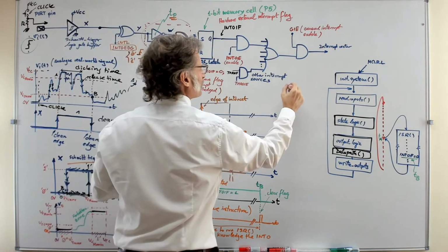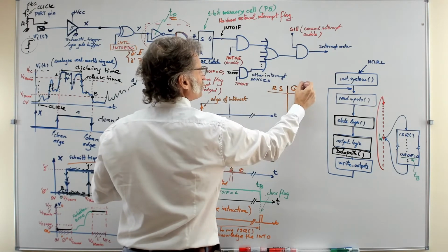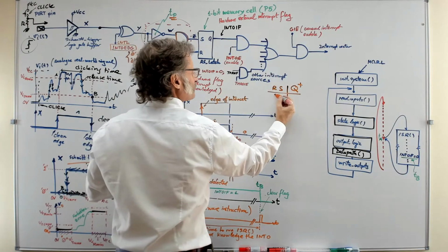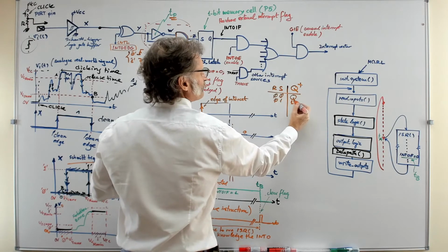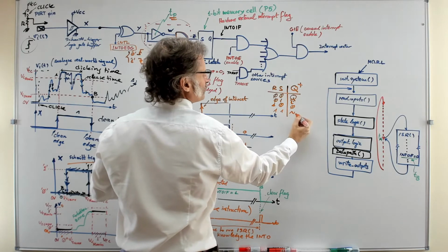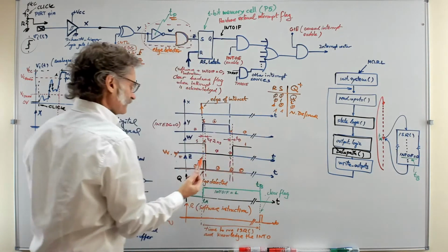And you know how an RS latch works, right? Remember, RS, and this is Q in the future, the Q after some nanoseconds. 0, 0, keep the value; 0, 1, save a 1; 1, 0, save a 0; and 1, 1 is not defined. Very well, so look at this.